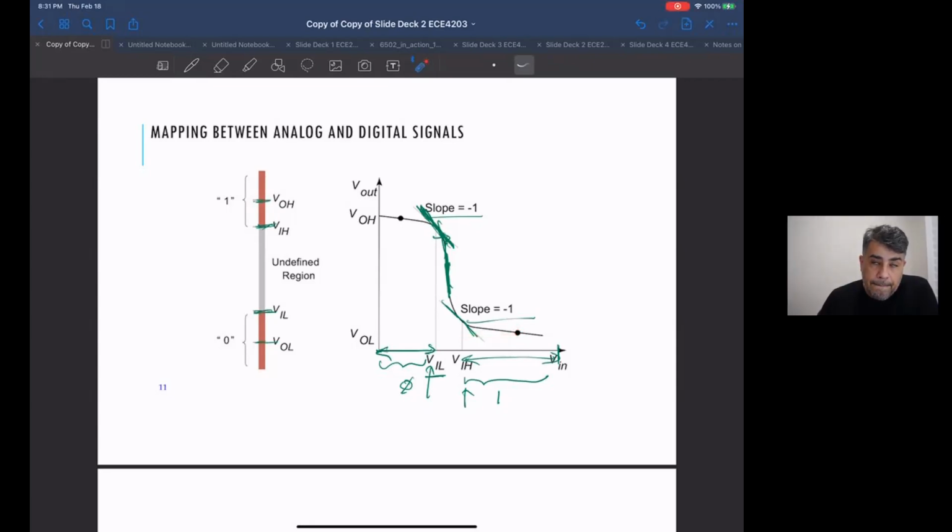So this low noise margin is like the difference between the two. What it's looking at is you have one inverter driving another one. This one defines the output low, the lowest it can possibly pump out. And this V input low is the highest this input will still accept as a legitimate zero. The difference between those is your noise margin for a zero, or noise margin low.